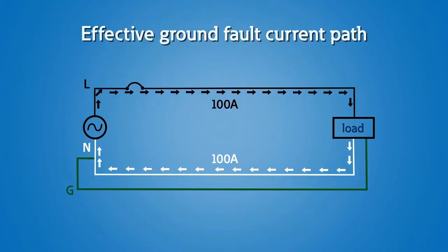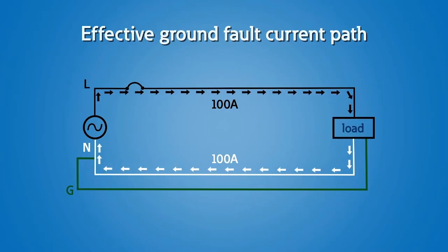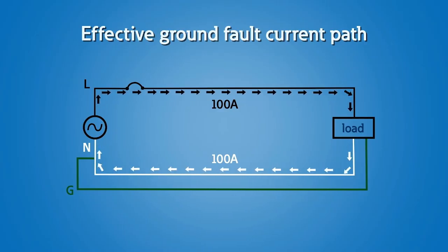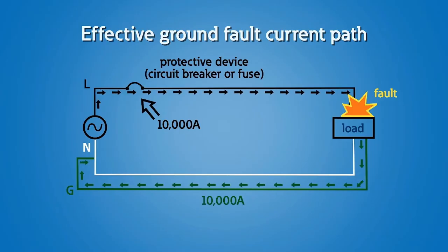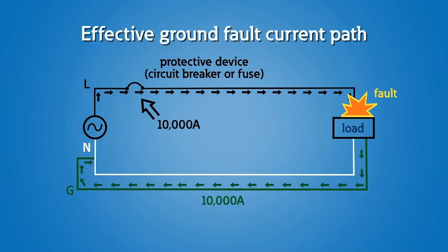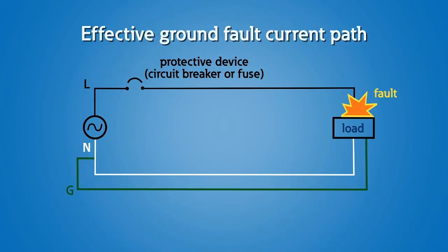Why are we talking about this? Why do we worry about grounding and bonding? We want to establish an effective ground fault path, and we also want to think about touch potentials or step potentials, for two different reasons. First, the effective ground fault current path. We're intentionally constructing a low impedance conductive path that's designed to carry the fault current from the point where the ground fault occurs in the system back to the source. And the reason we do that is we want to make sure that we open the overcurrent protective devices, which could be equipped with ground fault protection of equipment or GFCI protection. We want to make sure that we open those and give enough current for those to detect that fault.